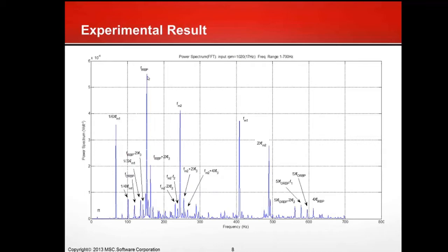There are a lot of small peaks, for example 1/3 of the gear mesh frequency of the first stage.